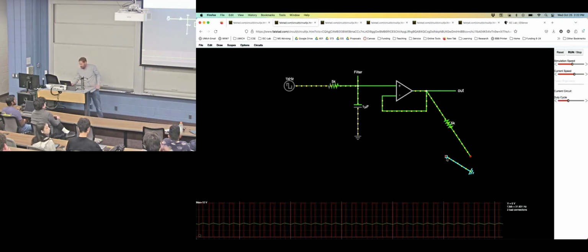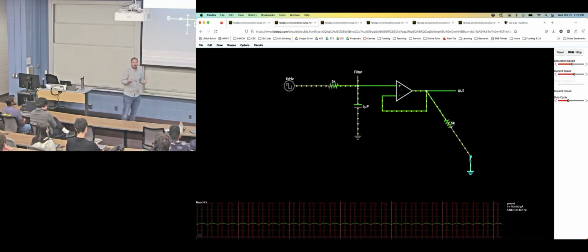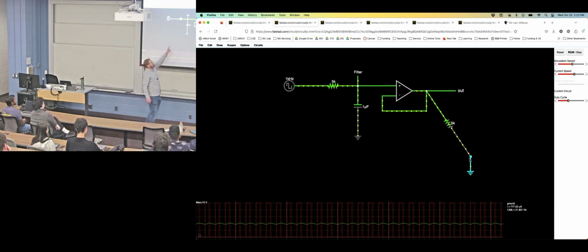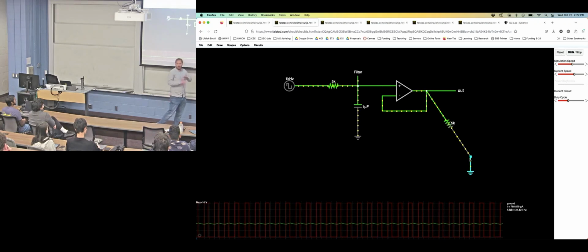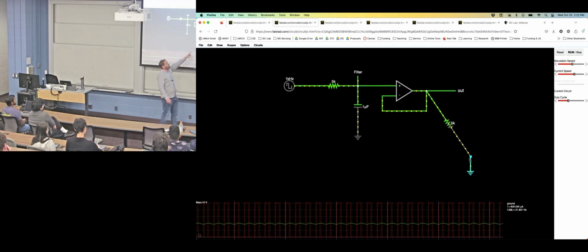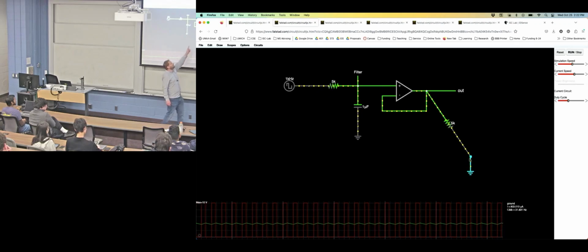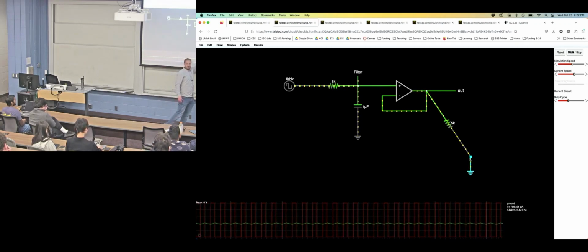So does it just like scale it more? Nope, doesn't scale it. This is a voltage follower. Sometimes we call them a buffer. So whatever the voltage here is, it's going to faithfully reproduce over there, okay? And that's all this topology does. It just reproduces it. But it doesn't matter what the load is now. Here, remember, we put a load on this, it browns the thing out. It starts sucking too much current around here. This op amp, being an active device, will supply as much current as is required to keep that voltage there.